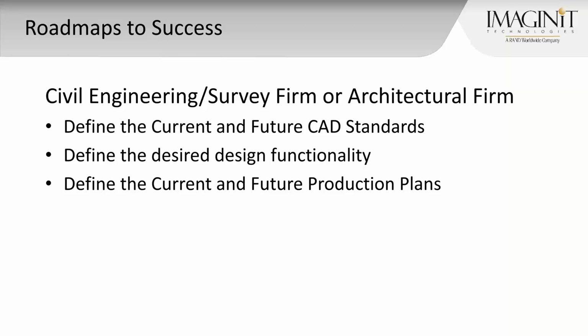And so once we have those CAD standards, from the drafting perspective of levels and layers, they can be put into that translation table. The translation table really controls the major portions of the process. So levels to layers, cells to blocks. Line types is always one that causes problems in the translation, because the customization of a line type in MicroStation differs from the customization of the line type in AutoCAD. So the dashes, the dots, and things of that nature are straightforward and controlled by the line type scale. But as we have custom line types with characters and things of that nature, those have to be recreated within the AutoCAD environment so that we can tell it to go from this custom line type A in MicroStation to this custom line type A in AutoCAD. And so those have to be done.